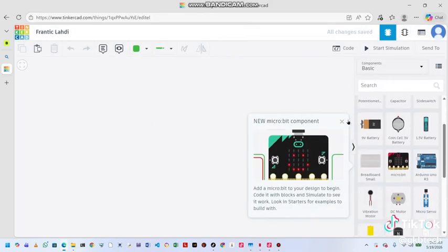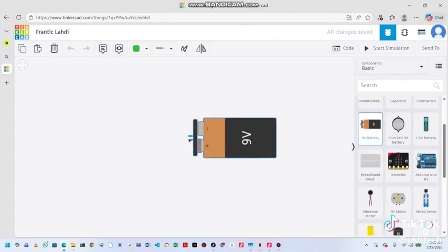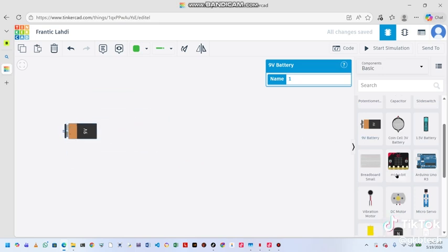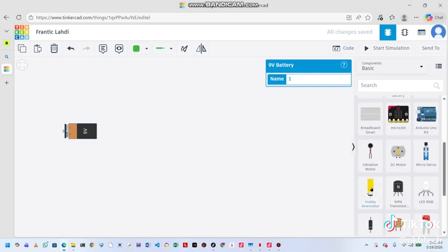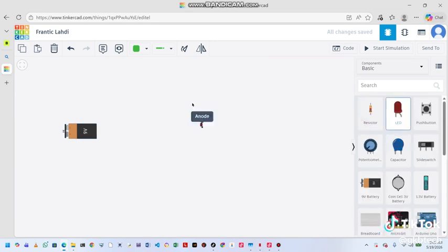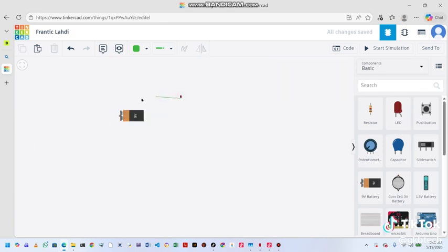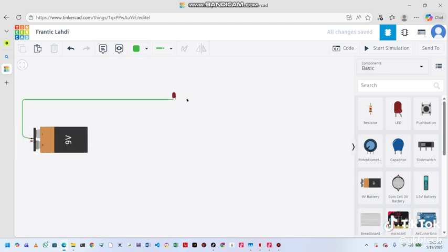So simply to build a circuit, you just drag and then drop the component there. You can zoom in and out as well. And let's say we are building a simple LED that should switch something like this. So how do we connect this? We know this is the positive, and this we send to the negative terminal, and then drag it somewhere here. I believe here is fine. Then we connect it onto the terminal there. And then we do the same for the positive.